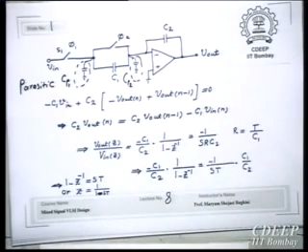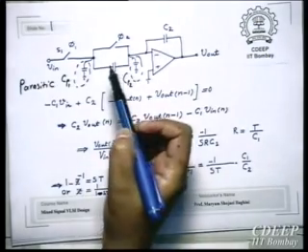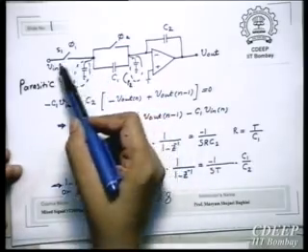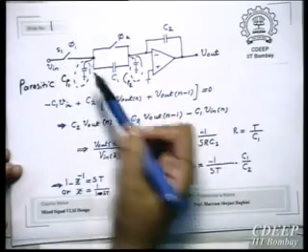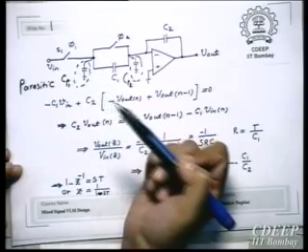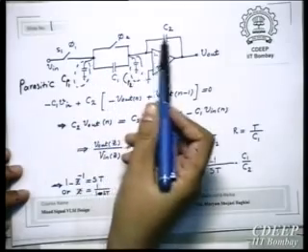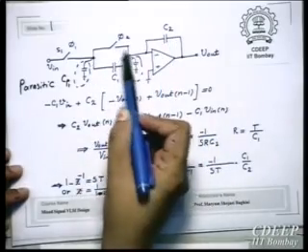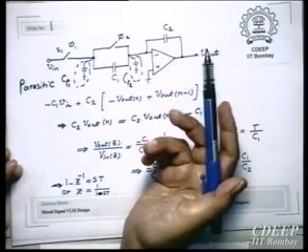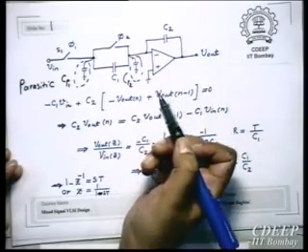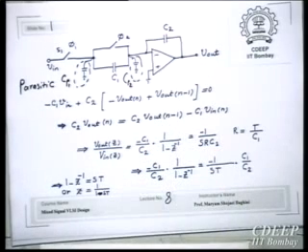Actually here I don't see any problem, because this parasitic capacitance is connected directly to Vin at the left side. This cannot create any specific problem. And charge transfer will be done in this state. And this capacitor C1 will get discharged completely in phi 2. Therefore, here I don't see any problem.